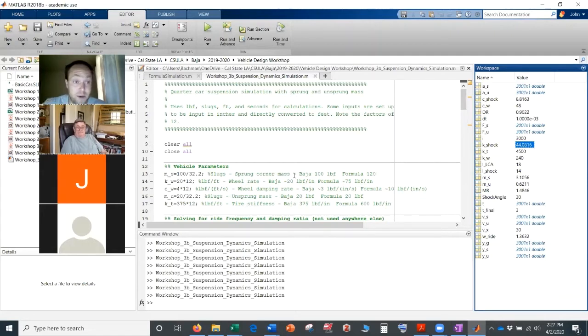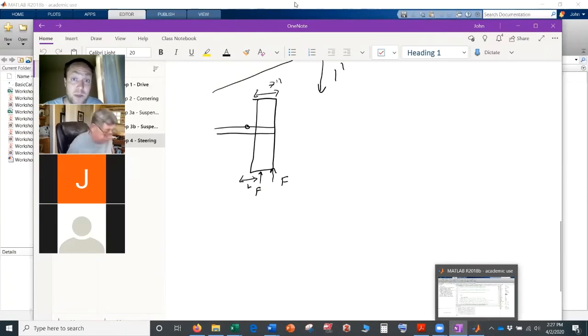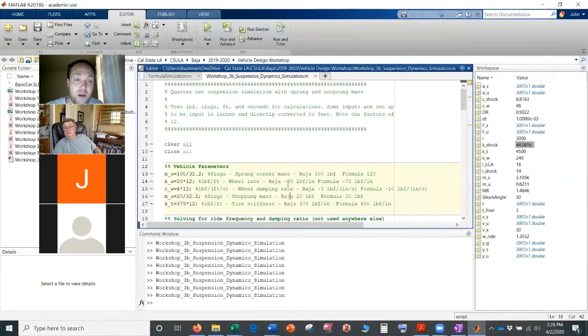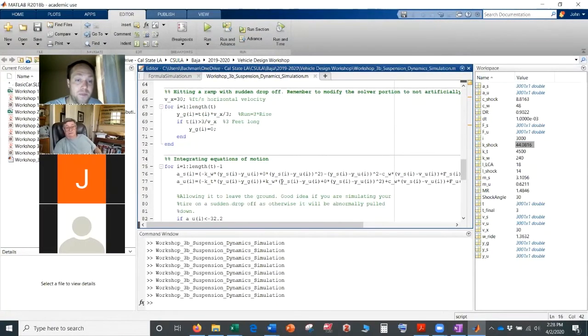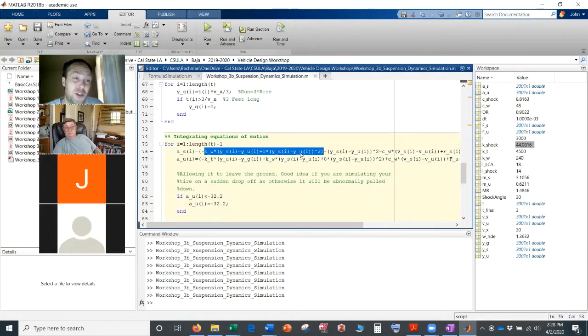So that was basically a little summary of everything we've done up to this part, bringing it all together. And you can see, it's not critical to get the right damping ratio and stuff, but to get the right responses from your car, right? And the other thing we wanted to make sure is that in models like this, for example, you could have your stiffness be a function of the displacement squared. So you can model nonlinear stuff, right? Which is really hard to do with analytical solutions.